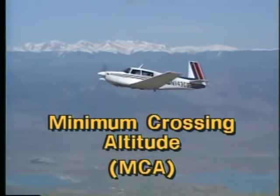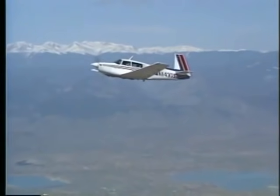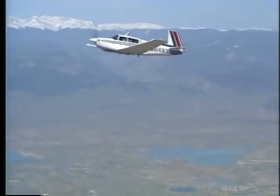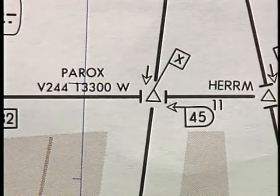A minimum crossing altitude, abbreviated MCA, is designated whenever intervening obstacles prevent you from maintaining obstruction clearance during a climb to a higher MEA. The MCA is shown by an information grouping consisting of the Victor airway number, the crossing altitude, and the direction of flight. A flag with an X is placed at the fix where the MCA applies.